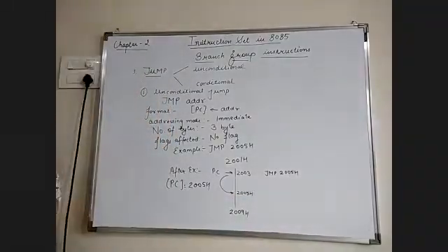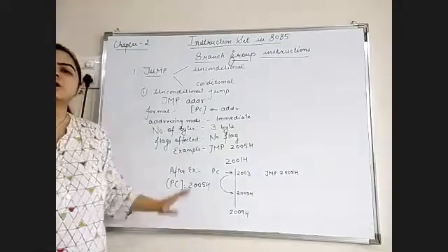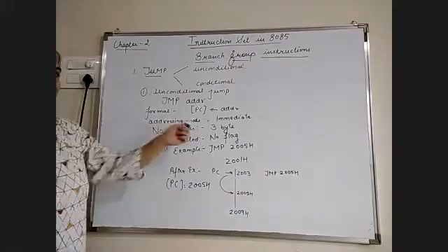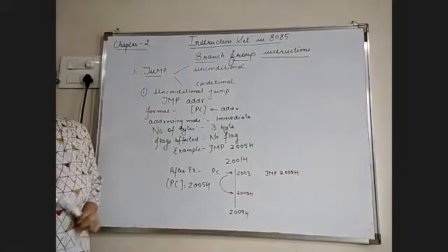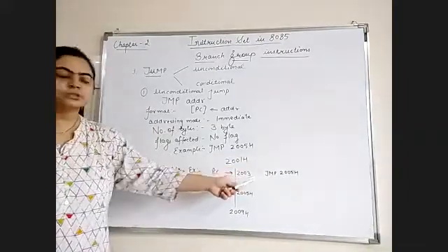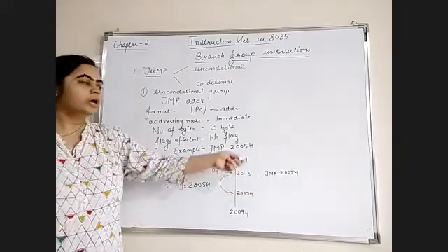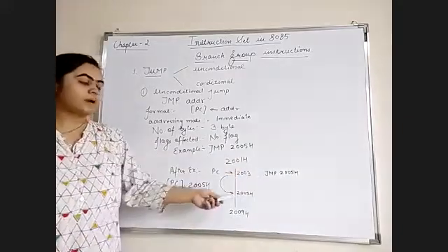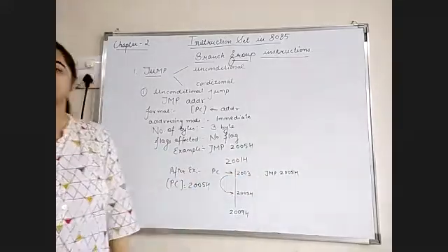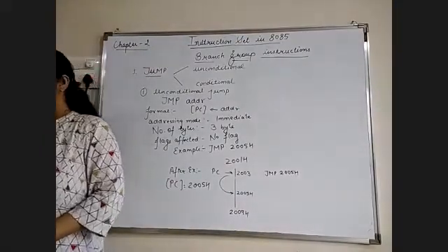This is known as the unconditional jump, meaning the microprocessor can jump to any location specified in the instruction without checking any condition. Here no condition is written, so once this instruction is encountered in the program, it directly goes to memory location 2005H. Is it clear?